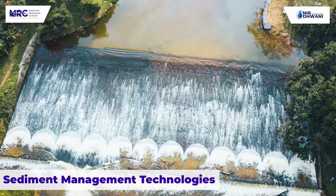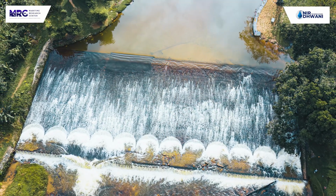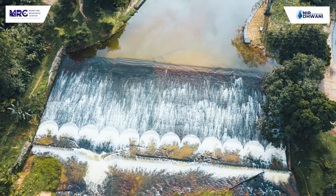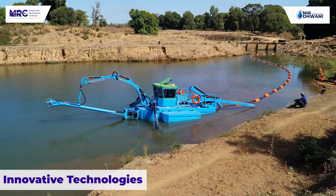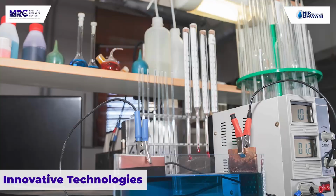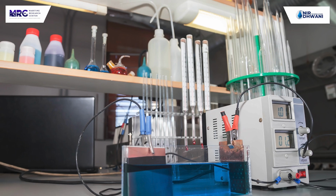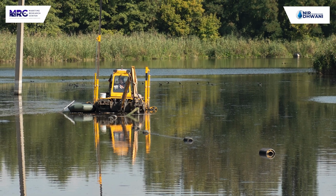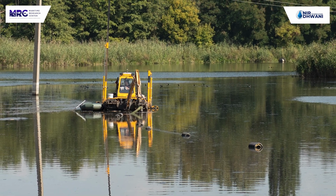Controlled release of water to flush out the sediment from reservoirs or other sediment accumulating areas is also done using sediment sluicing. Then there are the innovative technologies of environmental dredging, which is low impact dredging techniques to minimize the environmental disruption. We can also use microbes to generate electricity from the sediment, which can help in sediment stabilization. Water injection dredging is also used, which uses water jets to resuspend sediment into the water column, allowing the natural currents to transport it away.